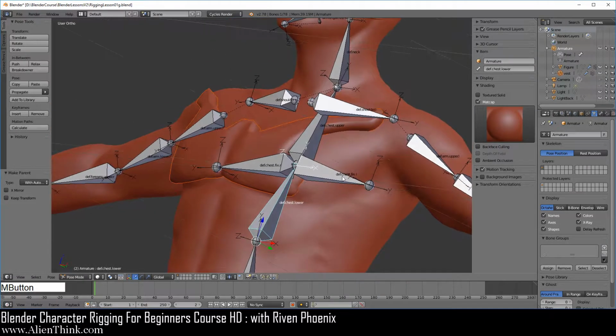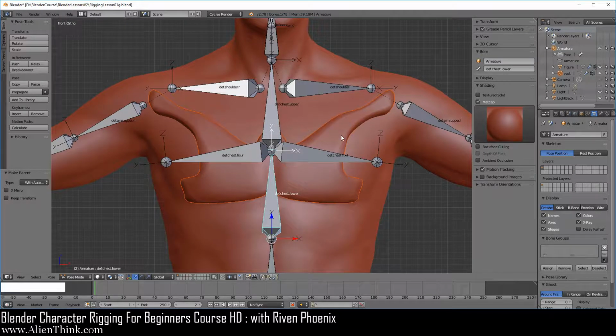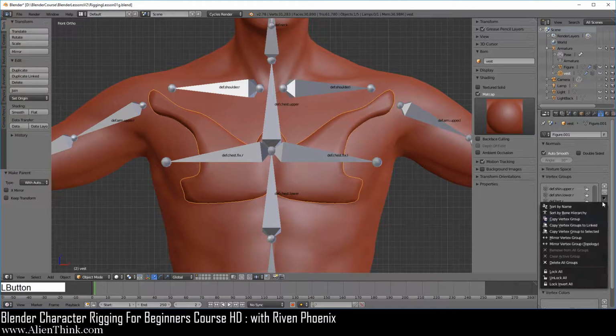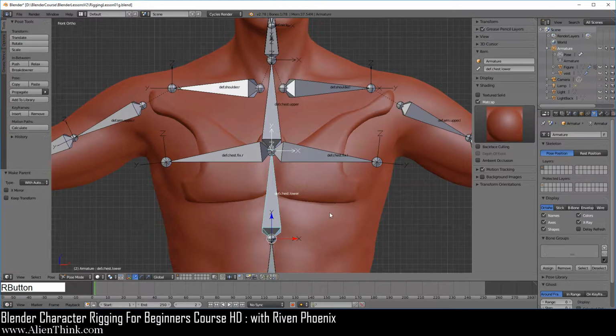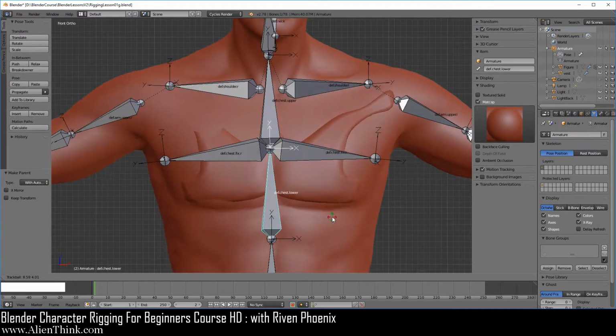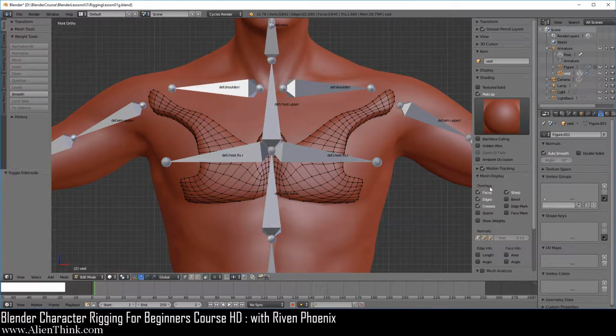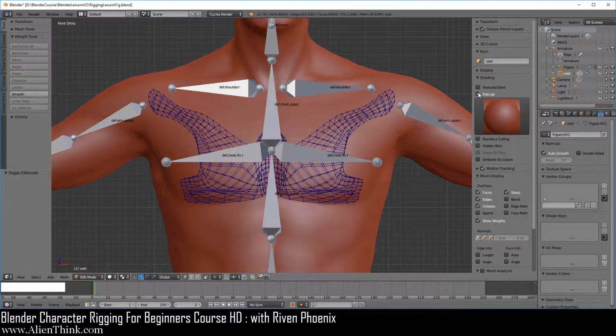But what we want is to capture the vertex groups that are already established on the figure onto this object. So the way we're going to do this is use that concept of weight transfer. Press the 1 key. Go ahead and click on the vest object, go to the data tab, and wipe out all the vertex groups. So this means that if we click over here, press the R key 2 times, the object is not going to move. Go ahead and click this object, go to edit mode, and make sure you do show weights and turn this off because we're seeing wireframe over here.